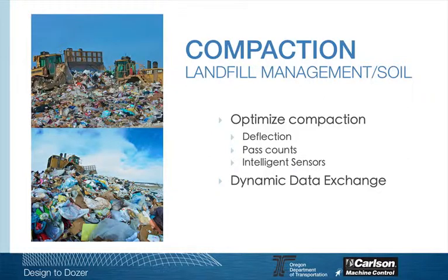Another feature that the technology offers is dynamic data exchange, and by this we mean if I have, let's say on a landfill, compactor A and I have compactor B, and they need to make 3 pass counts to reach optimal compaction. Well, every time compactor A goes over a particular area, that would be 1 pass count, 2 to go.